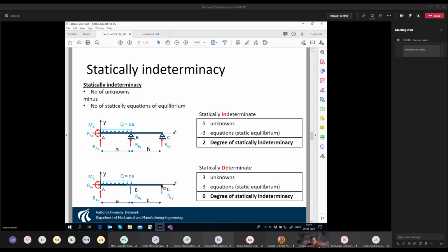So this is, again, I hope it rings a bell. This is the same story as before. We introduce compatibility conditions. We say that in this system, the forces RB and RC are in the amount which ensures that this point doesn't move upwards or downwards, and this point also doesn't move upwards or downwards. So when we introduce these two forces, we immediately introduce the conditions that the displacement at this point must be 0 and the displacement at this point must be 0.